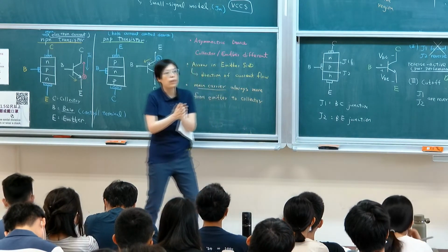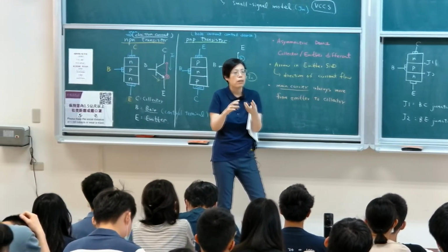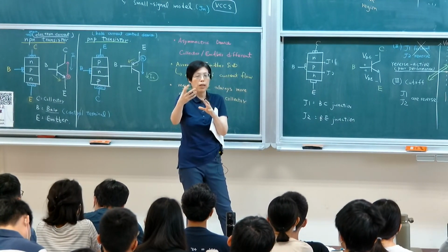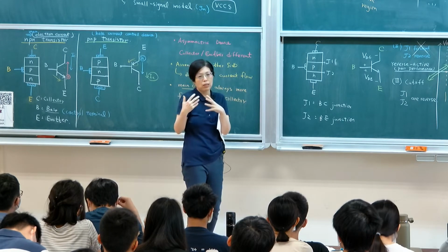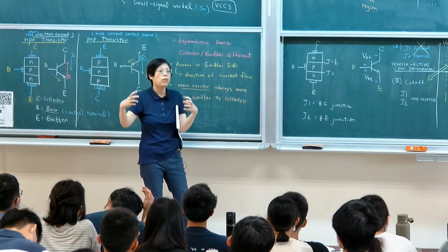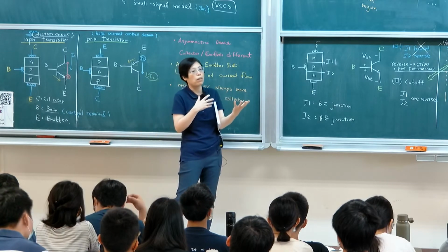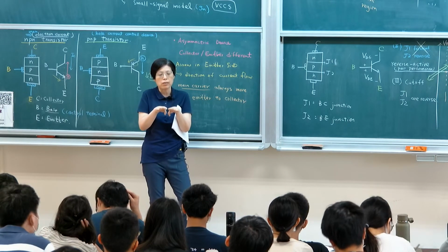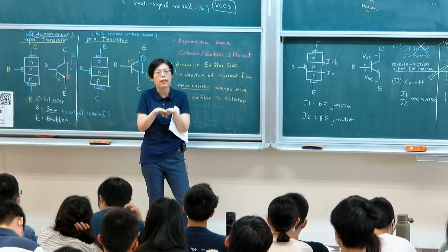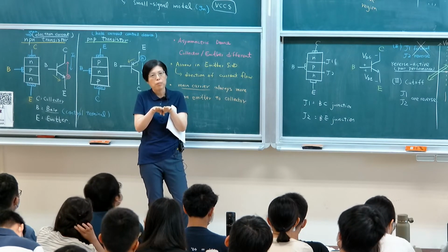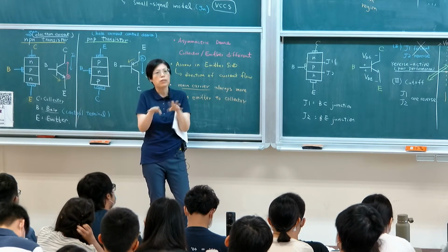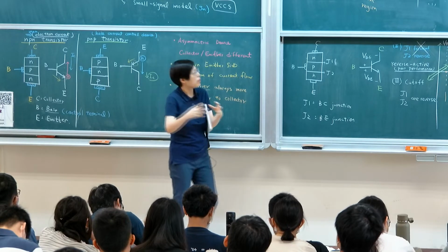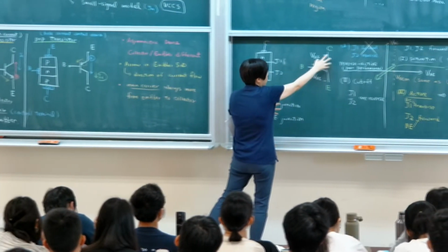But because the current comes in two types, electrons and holes, I'm only taking electrons. My suction system, or my vacuum, is selective. It only selects electrons, even though if I forward bias a PN junction, there's electron current and hole current. Remember, the diode current is electron current and hole current. So if you think about a bipolar junction transistor, the analogy I use in most cases is a current splitter. It splits electron current and hole current. The vacuum only takes in electron current, so the hole current will be provided by the base.